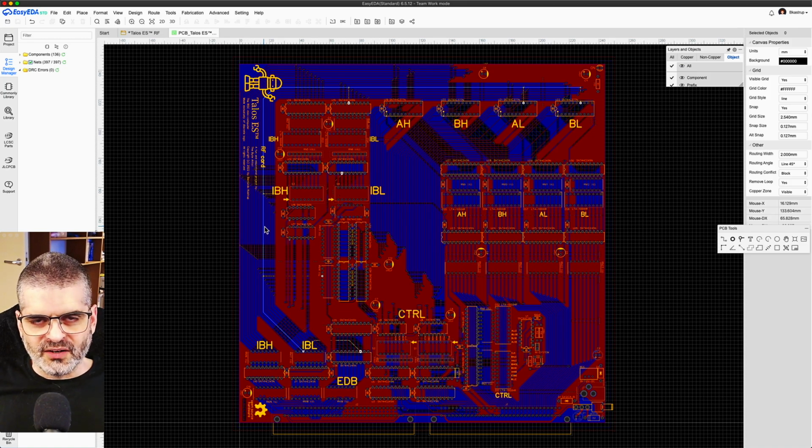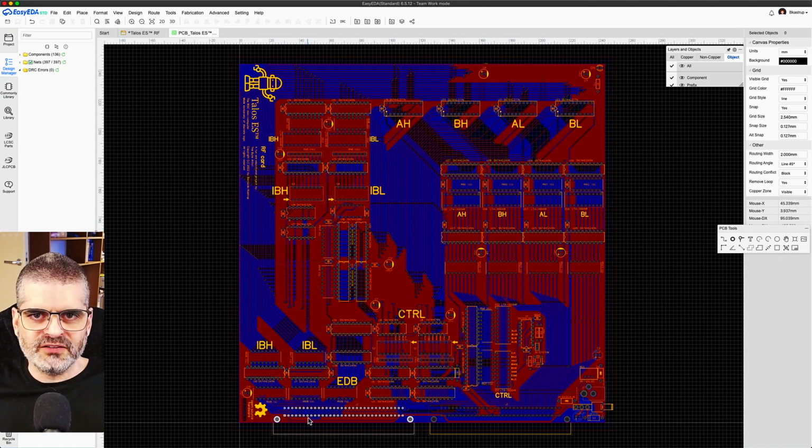And this branching out is what causes reflection, because each segment of the branch has its own resonating frequency, and then because the rise and fall times of these signals tends to be very short, you have higher harmonic contents which will resonate differently in each of the branches and therefore reflect and produce ringing with different frequencies. We absorb all that, well, not all that, but a lot of that with these 33 ohm resistors. And on the other side, it's to absorb the reflections from the backplane connector, which is a major impedance mismatch.